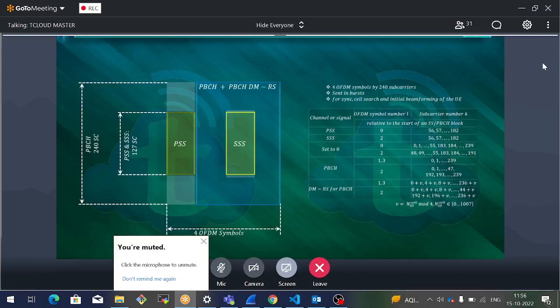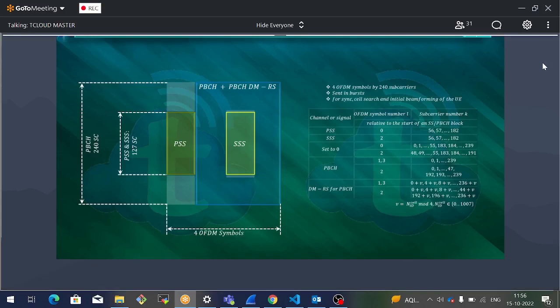After mobile successfully decodes this synchronization signal block and reads it, it will be able to find out what is the SSB block number that is going on, what is its signal strength, and various crucial details about the cell, like the system frame number and other technical parameters that are needed for mobile equipment's further operations.